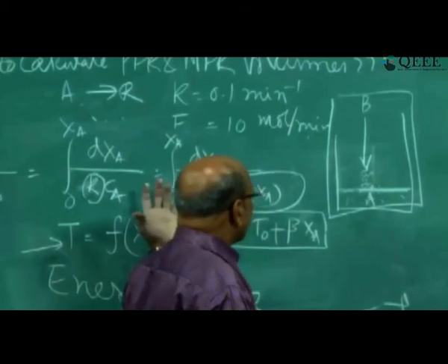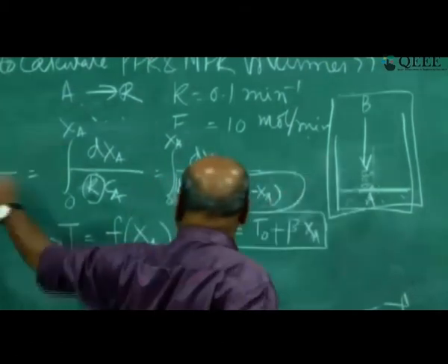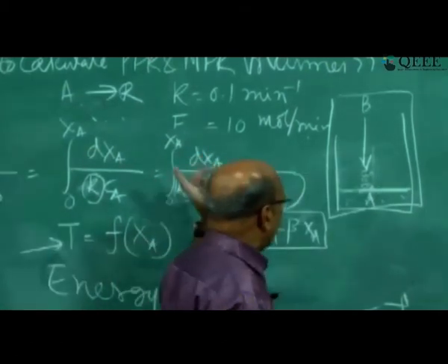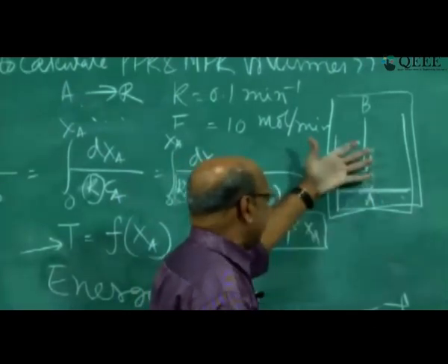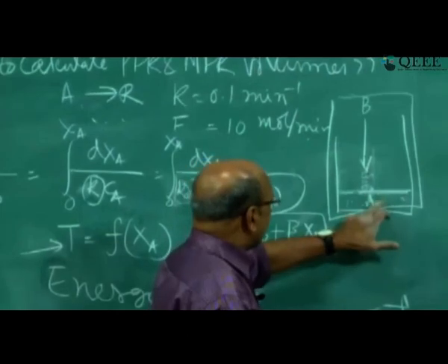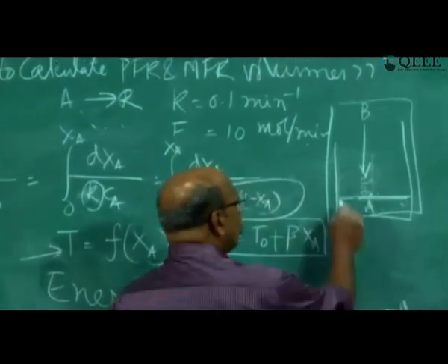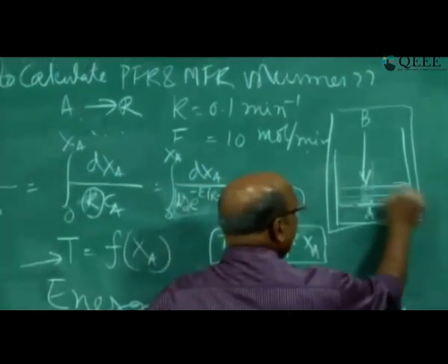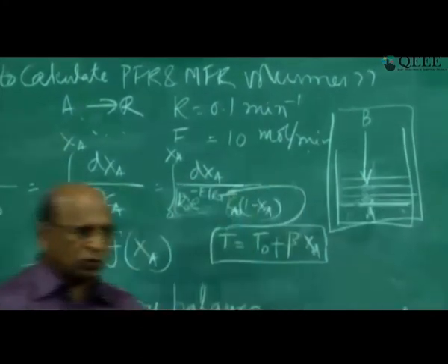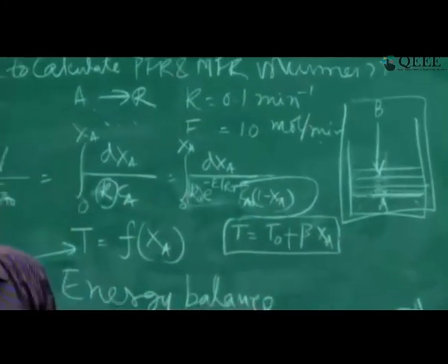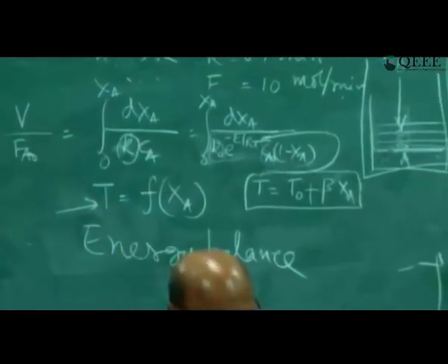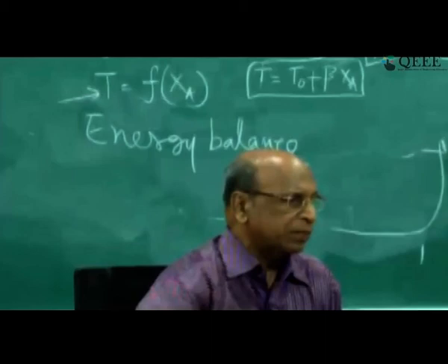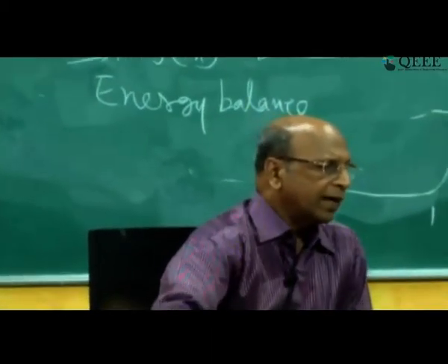But the procedure is again writing input, that universal equation I have written for batch reactor, mixed flow reactor, plug flow reactor. The procedure is exactly the same. But one extra equation you get here because the volume is increasing slowly when you are adding drop by drop. If you take that into account, then you can solve that. But the answer is mixed flow reactor is different and fed batch reactor is different. You cannot have the same equation. Okay?